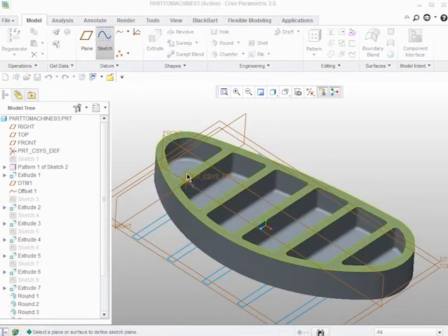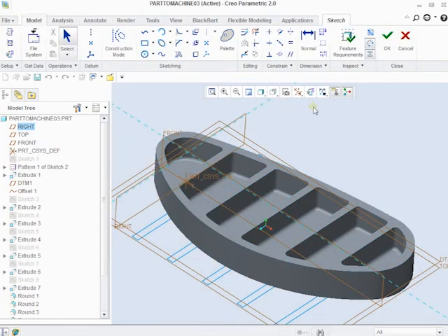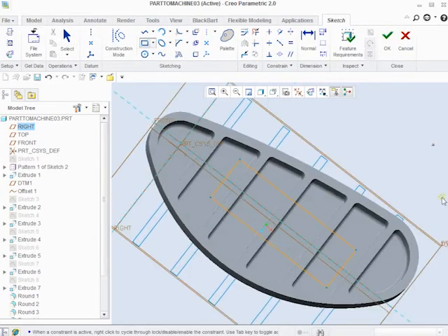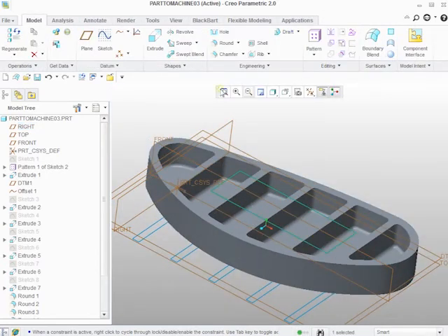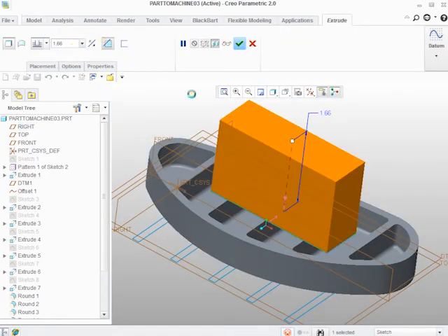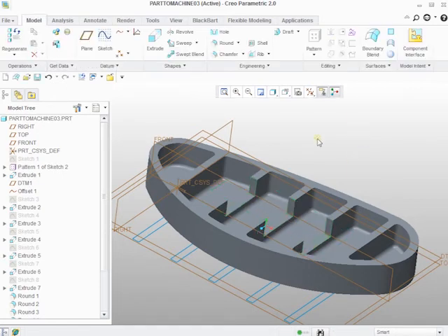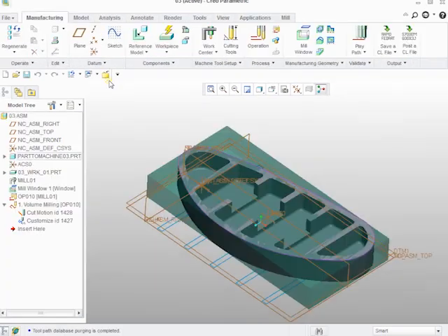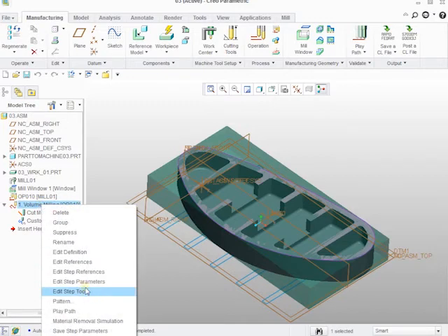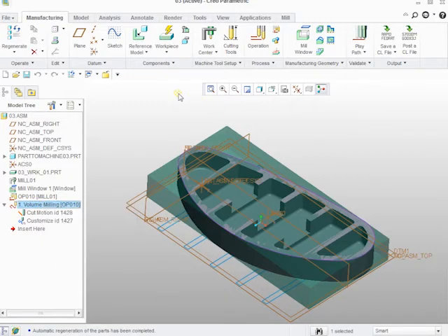So I'm going to make myself a quick cut here. Then I'll regenerate my assembly. Just make that a cut. Some approximate depth. Let's close out of that. And let's regenerate this assembly now. And let's recalculate this cutting path.